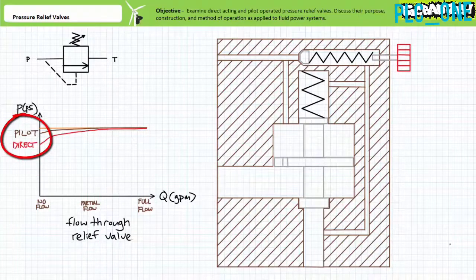This being said, a pilot-operated pressure relief valve overcomes the principal disadvantage of direct-acting pressure relief valves in that pressure override, the region between cracking and full open pressures, is considerably less, often on the order of only 25 to 50 psi. This means a system employing the use of a pilot-operated pressure relief valve will notice considerably less diversion of fluid operating at regions near the pressure set point. A pilot-operated pressure relief valve therefore allows a more predictable response to a user-imposed pressure limit.